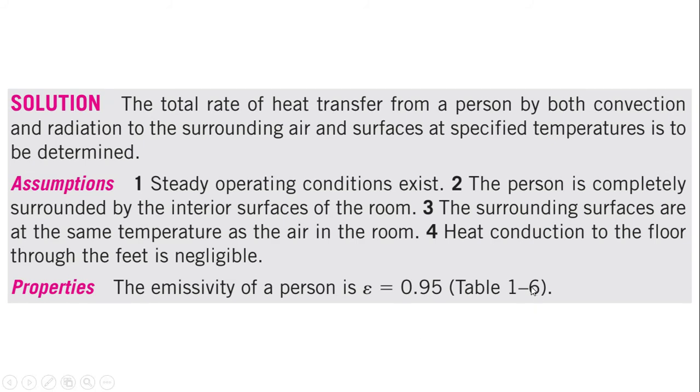So we'll take a few assumptions. Steady operating conditions exist because the temperatures are given here and they don't change with time. The person is completely surrounded by the interior surfaces of the room. So we know that the person is inside the room and the surrounding surfaces are at the same temperature as the air in the room. The air inside the room and the inner walls of the room are at the same temperature,